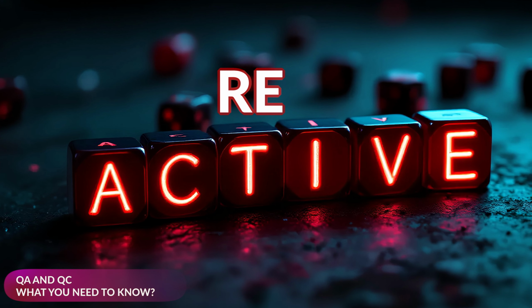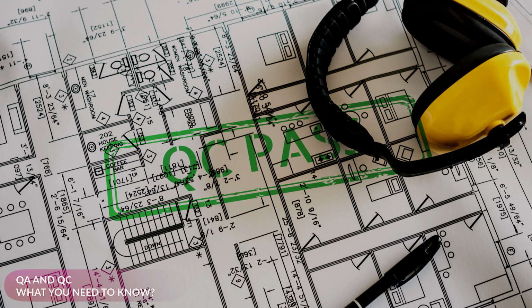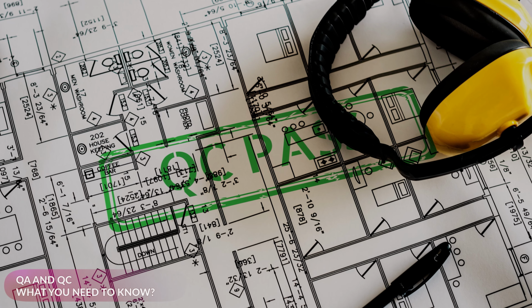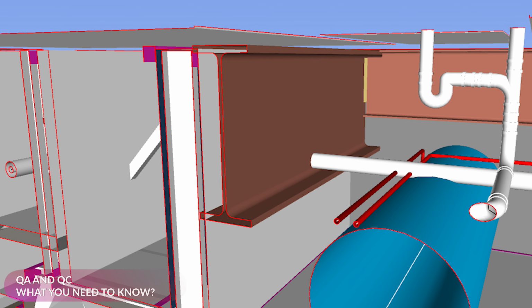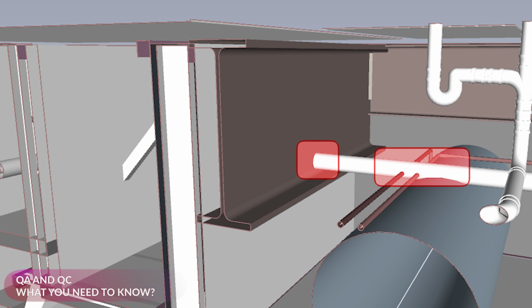Quality control, on the other hand, is about identifying and correcting issues that have already occurred. It's the reactive part of the process, ensuring that any mistakes in the model or workflow are caught and resolved before the project moves forward. For example, run an automated clash detection process that checks if any mechanical ducts or plumbing pipes are colliding with structural elements like beams or columns.